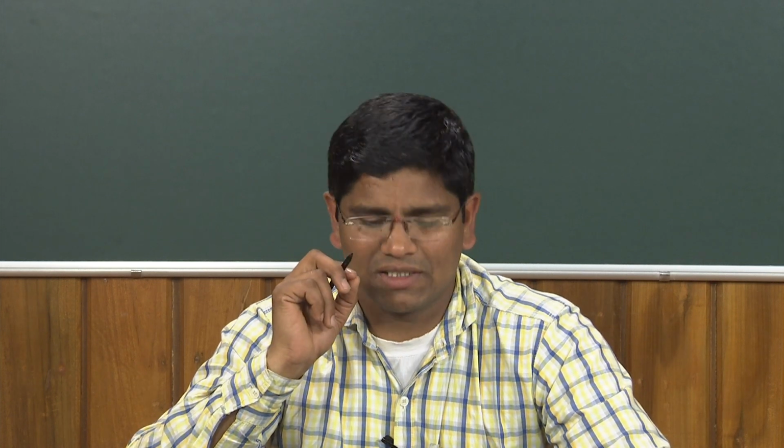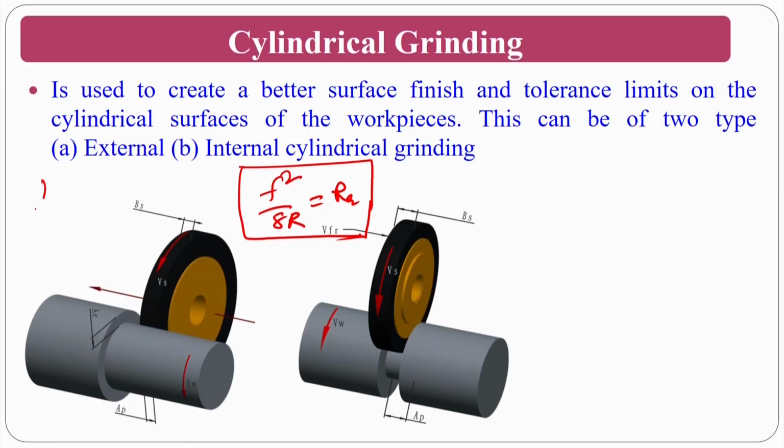But one point you should clearly notice in the grinding process is that the abrasive particles all possess negative rake angles. No abrasive particles will be like a concave surface like that. All the abrasive particles will mostly be convex particles. That means you will have negative rake angles. But the size of the abrasive particles is too small compared to your nose radius. The surface roughness you are going to get is very fine. As the particle size goes down, you will get very good surface finish.